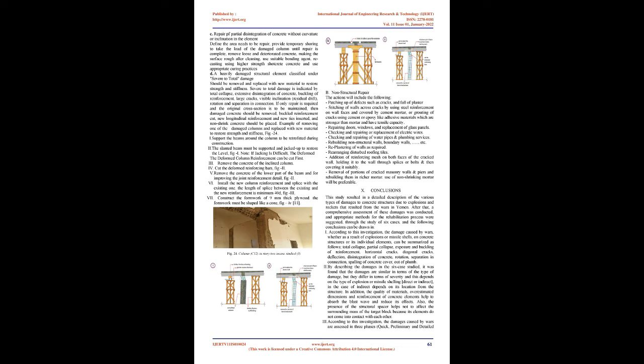B. Repair of cracks whose damage severity was slight. Non-shrink grouts are used to repair cracks, to fill voids, or to close the space between adjacent concrete portions. Epoxy grouts are recommended for conditions when high shear forces or positive bonding is necessary across a void. Low viscosity resins are used for small width crack injection, while higher viscosity resins can be used to fill larger